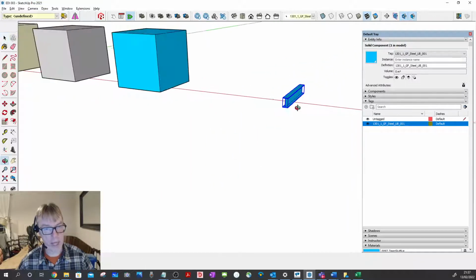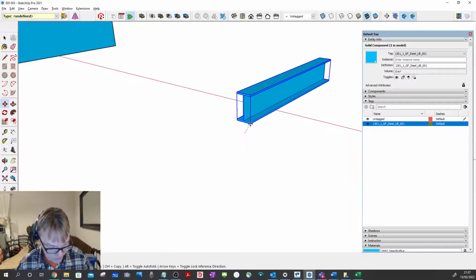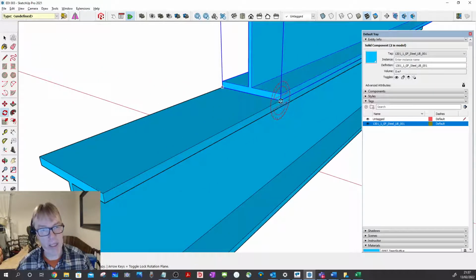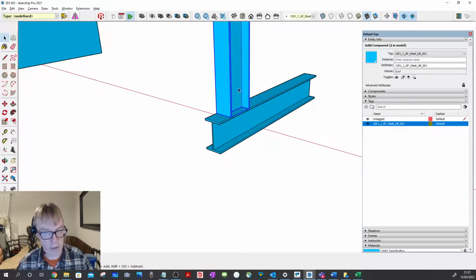And so that's perfect. I could now go and select that object, press Ctrl to keep the original there, and start making some sort of structure out of this. If I was to start to do that, I need to go and right click on that object, make that unique, go into this and give it a unique identifier, so it'll be number 2 this time. Select all of that, go down to tags, press number 2, and ask it to go on to tag number 2.